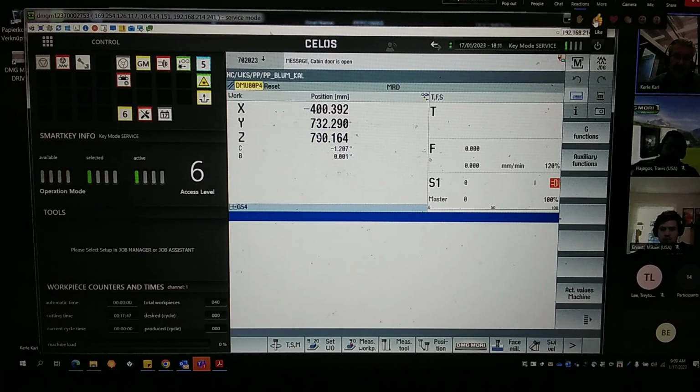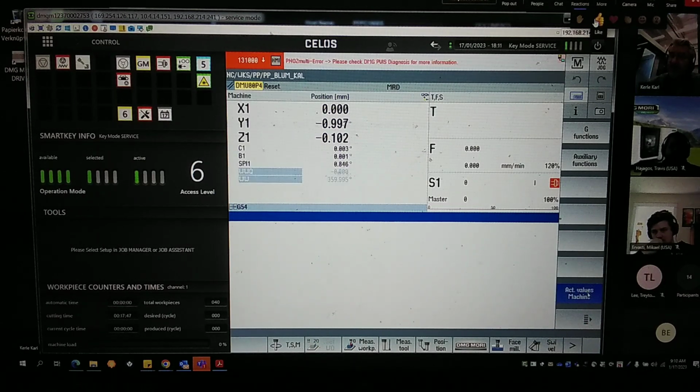Is this a help for us? No, boys. That's necessary for the operator. He has to check the positions regarding the 0-point offset. But for us, it's the worst case. Why? Here we have no reference to the real position regarding the 0 and the tool change position and so on. This could not be checked if the work coordinates are active. That's bad for us. Therefore, again, click the vertical soft key 7, actual values machine.